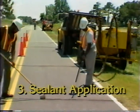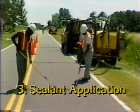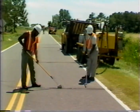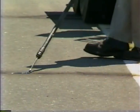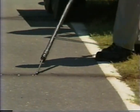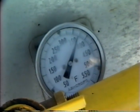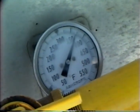The third step is sealant application. Proper application of the sealant is critical if the sealant is to perform effectively. A rubberized asphalt sealant is recommended. It exhibits the desired requirements for a good crack sealant. Maintenance of proper material temperature is important.